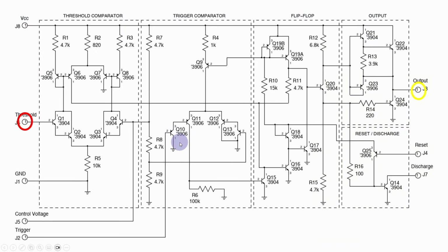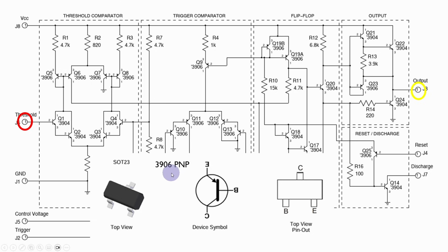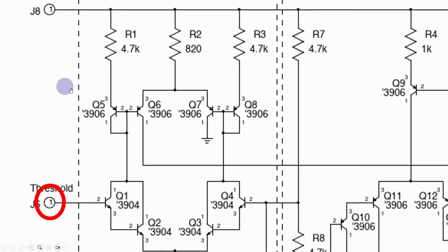Now this was the 555 diagram that we looked at in the earlier video, and if you remember, we've got both types of transistor here. We've got the PNP transistor, and what I did here is take the symbol that we just showed you previously and reverse it, because if you see on the diagram here, the way the PNP transistor tends to be used is with the emitter connected to the 5 volt supply.